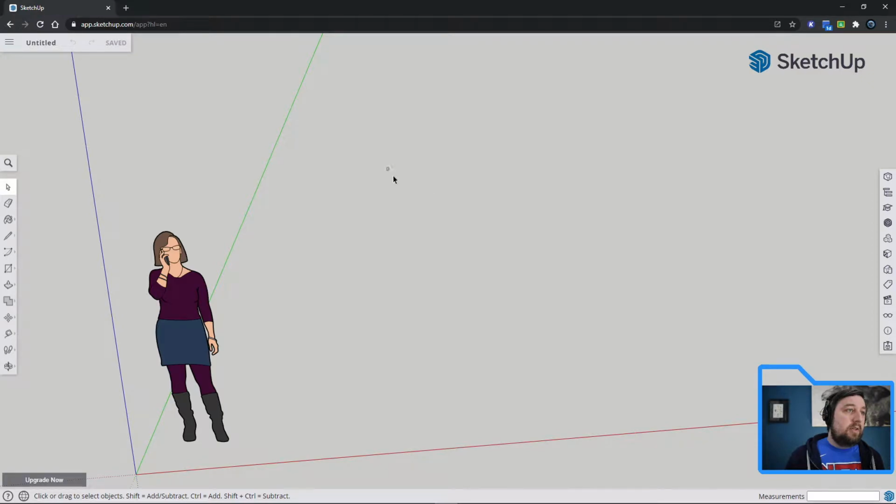Same kind of highlight deal as with AutoCAD. Dragging from top left down to bottom right, it's what's entirely inside the box that it'll highlight. Bottom right to top left gets dotted, and it's everything it's touching. All right, and then spacebar brings you back to your normal pointer.